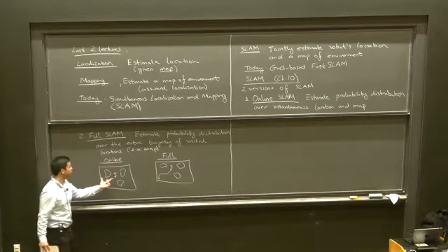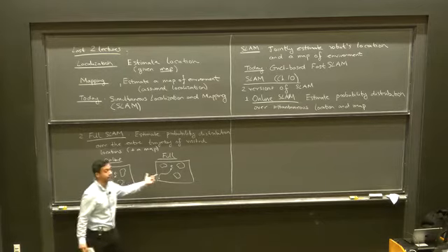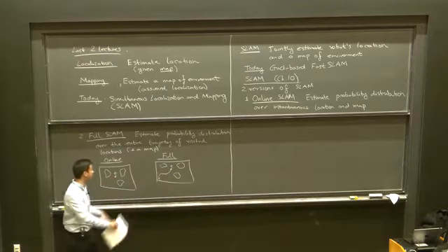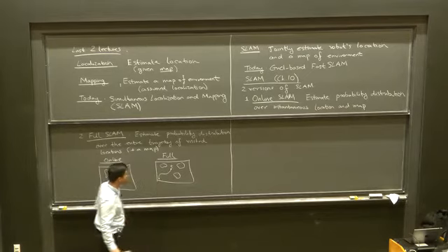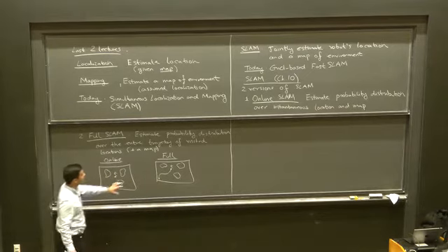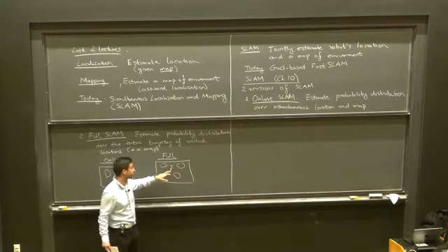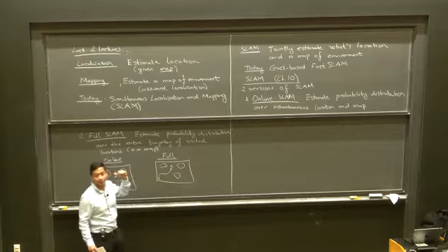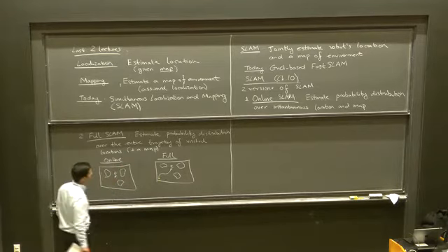In some sense, if you were able to do online SLAM, you could use that to get an estimate for full SLAM just by, at every time step, maintaining a belief and concatenating those beliefs together, which gives you a belief over the entire trajectory. But with full SLAM, you could do a bit more. If you get some new information at time t, you could refine your estimate of where you were previously. So which version of the problem you look at depends on the context.